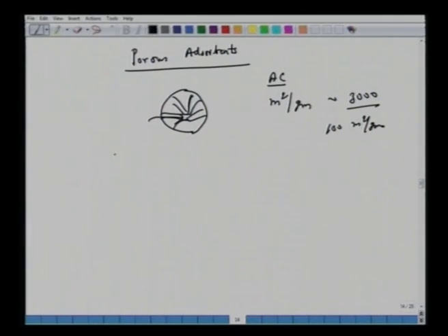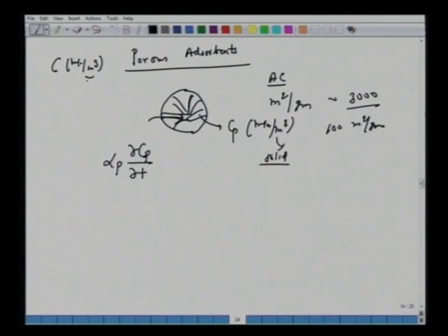and you can imagine this would be another complexity here, say del Cp by del T. So now we are writing Cp in moles per cubic meter of solid phase. Remember, first we had C in moles per cubic meter of gas or liquid phase, the bulk phase. Then we said that there is C at R equal to Rp, the solid external phase. Now we are talking of Cp, which is inside these pores here.